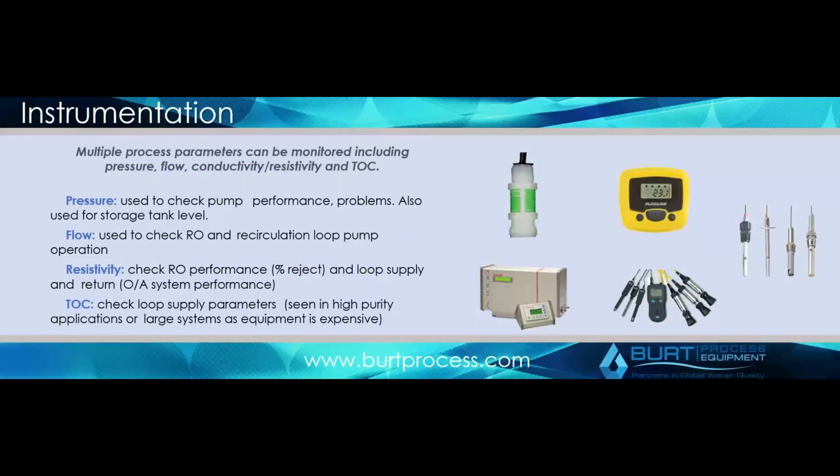We haven't touched too much on this, but throughout any high purity water system, we'll go through a case study here in a minute. You're going to see there's a lot of instrumentation involved with these systems, between pressure monitoring on the pumps. We talked about resistivity. You can get TOC monitors as well for this system. And the more instrumentation, sometimes when you get into more validatable systems, can get relatively expensive in those cases, but you can in a lot of ways measure almost any one of the parameters which is involved within a system.